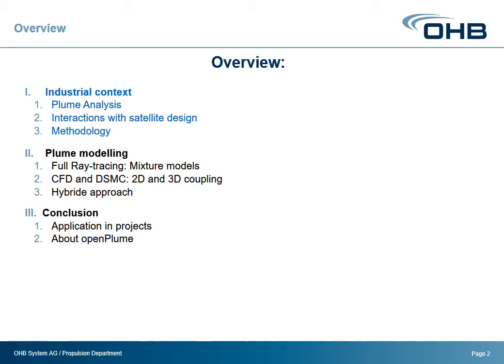The second part, which is the main part of this talk, will be about the plume modeling. This approach will be about the full ray tracing first. I'm going to show you and explain how we do this modeling, the CFD and DSMC 2D and 3D coupling parts, and then how we apply this in the projects. And the last point is about OpenPlume CP, our project that is free and available for download. I will come back to it later.